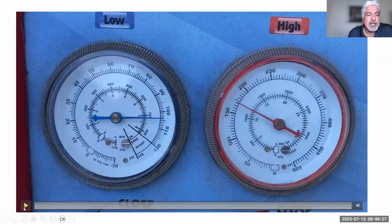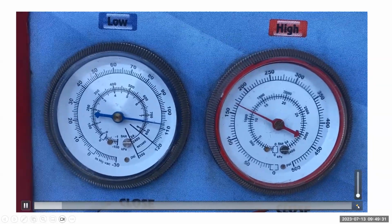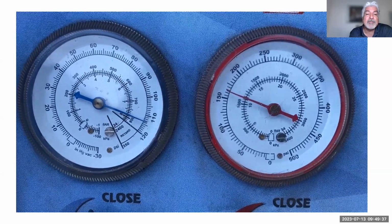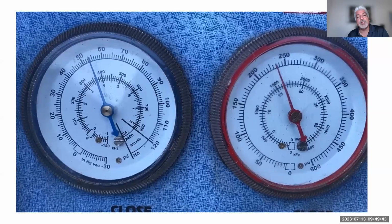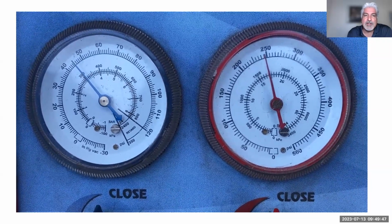But once I go ahead and engage the compressor, turn on the AC compressor, what's going to happen? Well, the AC's turned on, the blower's set on high, right? We're at the face. We're going to kick it on. All of a sudden, the compressor kicks on. The suction does its toll. It starts to bring the pressure low, and it pressurizes up against the expansion valve on the high side.